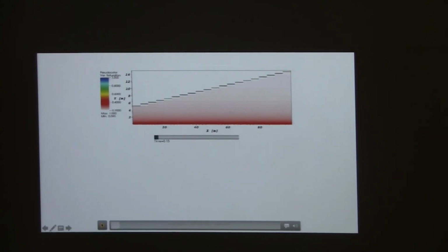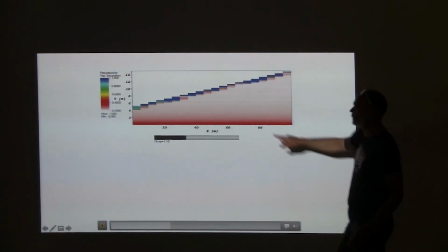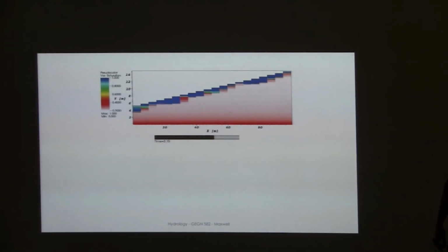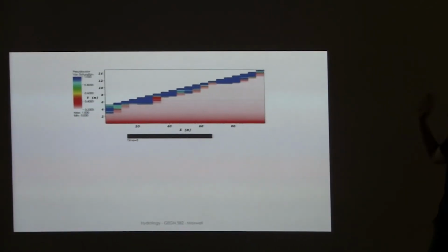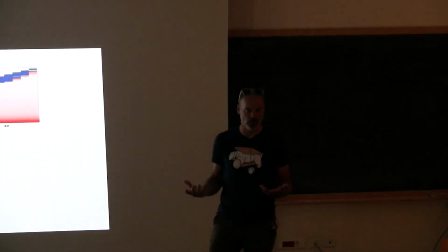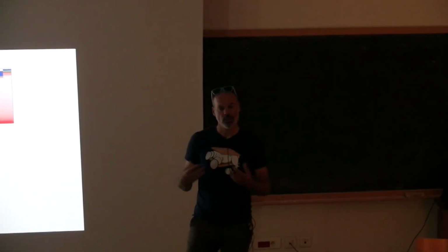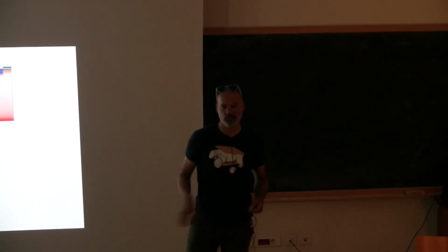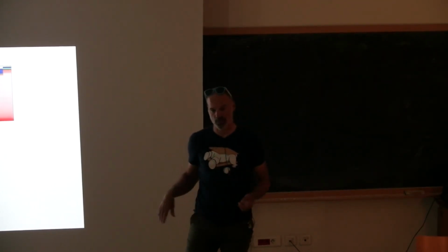So if we think about it, what's interflow? Well, this could be these fast heterogeneous pathways, right? Conceptually, these higher K, faster paths that are not distributed over the entire system. This is a lot like Jeff's interflow. You think of it as a heterogeneous subsurface storm flow, right? So you have these connected interflow pathways and you get very fast response.